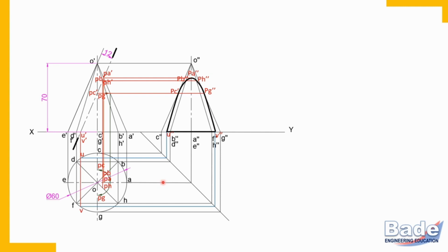So this is that parabola we have studied earlier in the same video. That is, when cutting plane line is parallel to its boundary generator, then section is a parabola. So we have completed that section in the parabola in the top view and in the side view. Remember, U and V are sharp corners and UV is always a straight line. So parabola, all P points we have joined with a curve, but U and V we have joined with a straight line, and that is a line on the base.